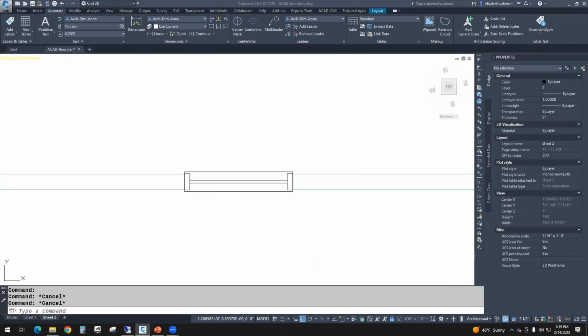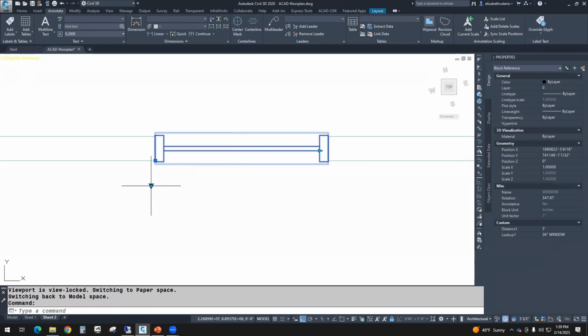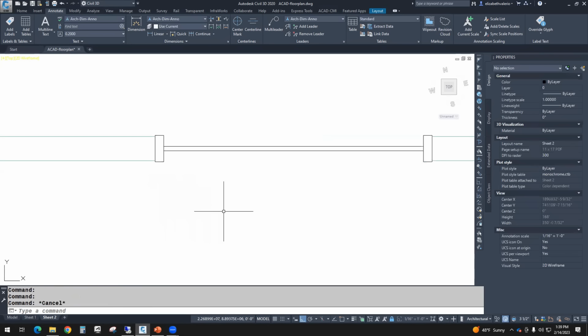Okay. So we see the window, we see the wipeout, everything's working properly, but I actually don't want to see that wipeout frame. So I put in the chat, you can set the wipeout frame equal to 0. That should turn it off. 1 equals show, 0 equals hide. So let's type wipeout frame, and then 0. Once it's turned off, you can test it again. It should work nicely.